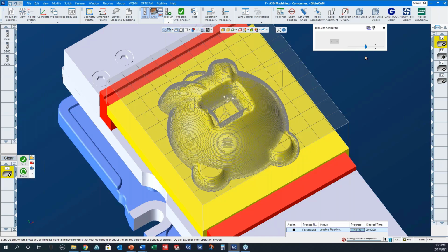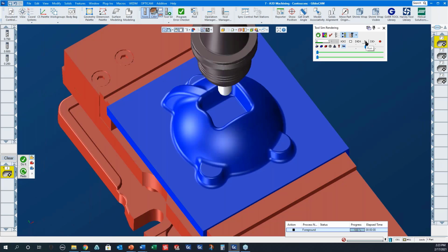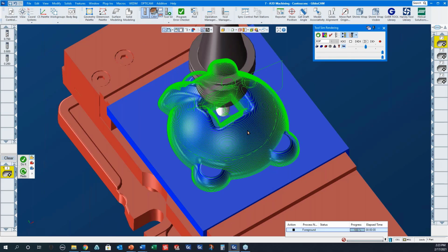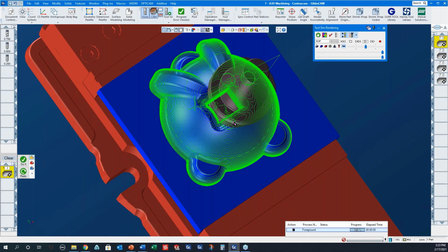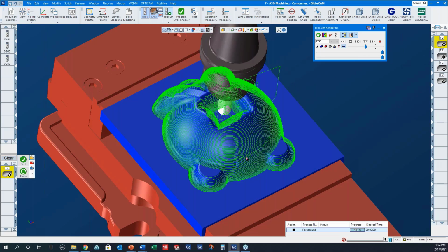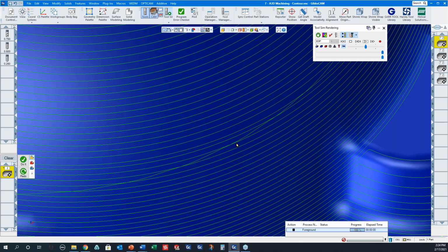This is contour cutting with a constant Z level. You'll notice by doing constant Z level, your step overs appear to be very wide here where the part's nearly flat. The next example is going to still be constant, but you can see these smooth step overs like we referred to earlier.